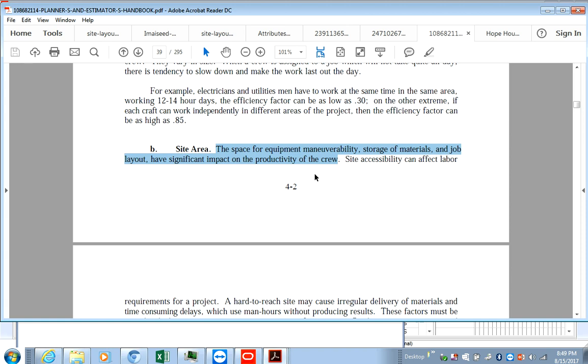You bring in the mobile crane, you fit in the high-level stuff. Then the electrical and the ceiling guys want to come in straight after you've finished, right? What happens? Will they still need that mobile crane? Of course they will. Will the guys who are doing the floor screening, etc., also need that mobile crane? No, they wouldn't. If they want to run their jobs concurrently, what would happen? You'd have a bottleneck with the mobile crane within the building, right?